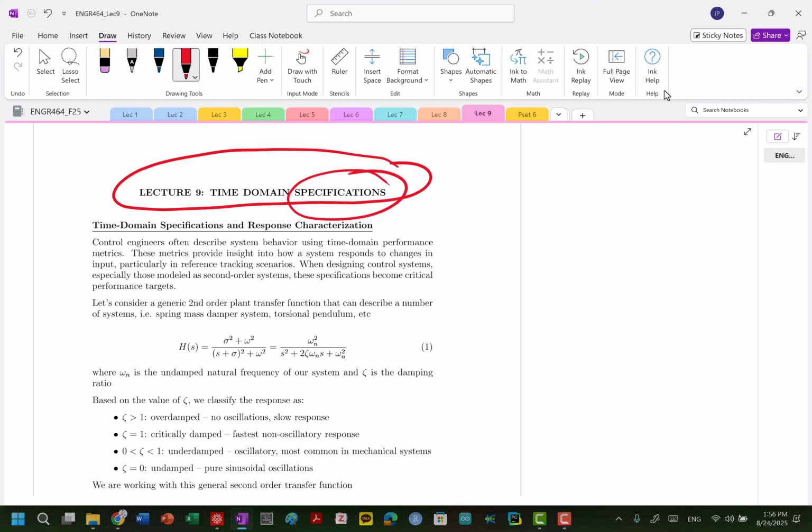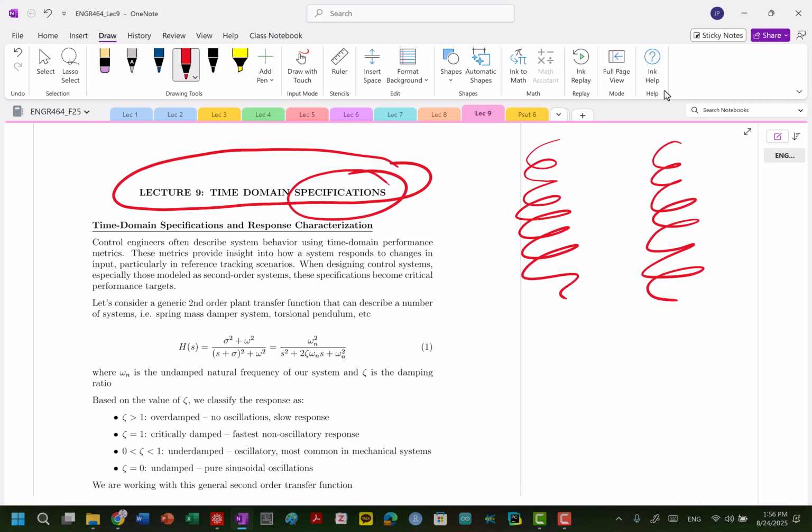So, for example, let's say I wanted to create my own universal testing system. So usually if you've done any work with an Instron, you have kind of these two rails that are ball screw driven. You have basically this top head with fixtures and a bottom head. One of those is fixed, one moves. Let's say the top is the one that's moving. You put your sample in between the grips. You put in tension, compression, et cetera, et cetera.